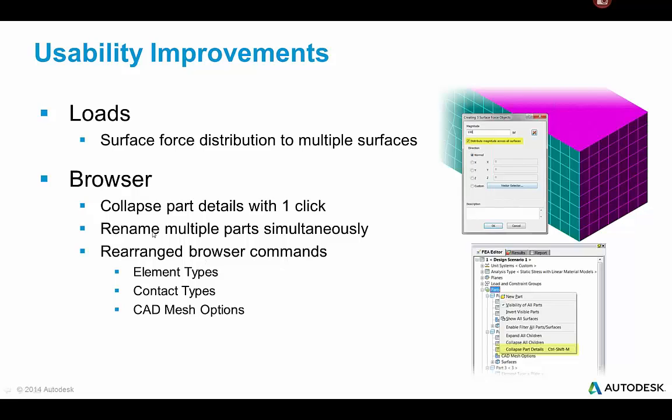Now you can also select multiple parts and rename them simultaneously. In the past, you would have to do this one at a time. And this is specifically useful if you have, for example, 10 bolts that you want to rename to the exact bolt size you're using. So then you don't have to do it one at a time. You can do it all at the same time.